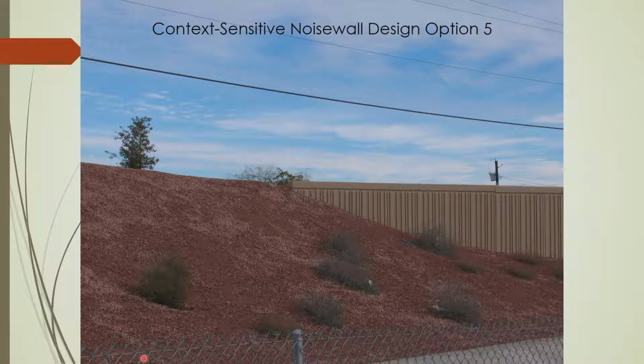So sampling it doesn't necessarily mean that we will always do this or we will never do this, but knowing the extent to which particular kinds of earth berm designs are preferred in places where that's an opportunity, then the designers will have some guidance on how to use earth berms if they choose to do that. And there are circumstances where they'll have excess dirt from excavation from building a roadway, and so an earth berm is an appropriate way to build a sound barrier. In other cases, it's not. So all of those other factors are not trumped by people's preferences for different kinds of designs. This is additional information that helps inform what they're doing when they're making decisions.